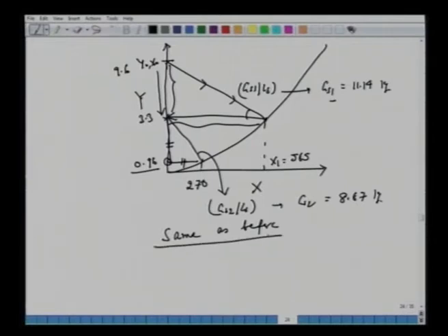Alright, so what we have obtained here is the same message. Whether we solve analytically or graphically, there is an iteration required, and this always happens when the number of stages is fixed. So if you are told that we have been given 2 stages, 3 stages, 4 stages, then calculate the amount of charcoal or amount of solid required for the treatment of the feed, one requires iterations, whether it's cross current or counter current.